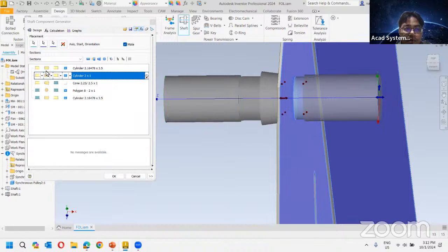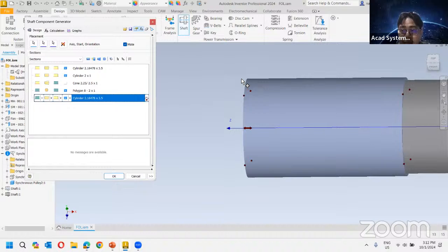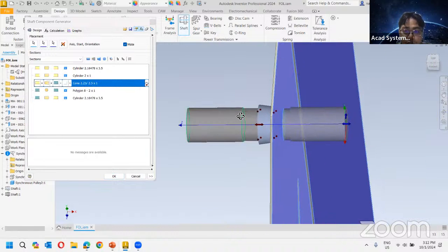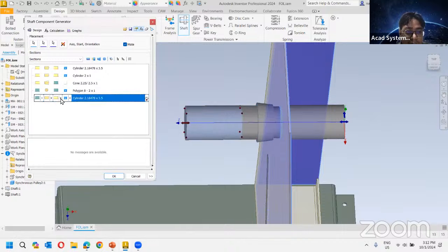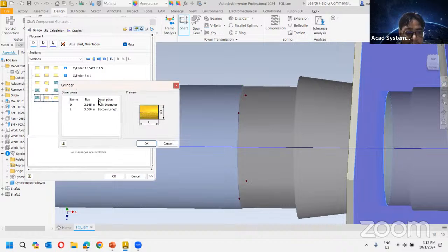So that is just a symmetrical rod that you can add. Other things that you can edit from here: if I take a look over here, I can also add a chamfer or maybe fillets at the end. So I can just select here. Okay, it's actually fillet from here. The reason why I cannot add some more is because it's right over here and it's way too small. So let me just increase the diameter, let's say around 2.5.